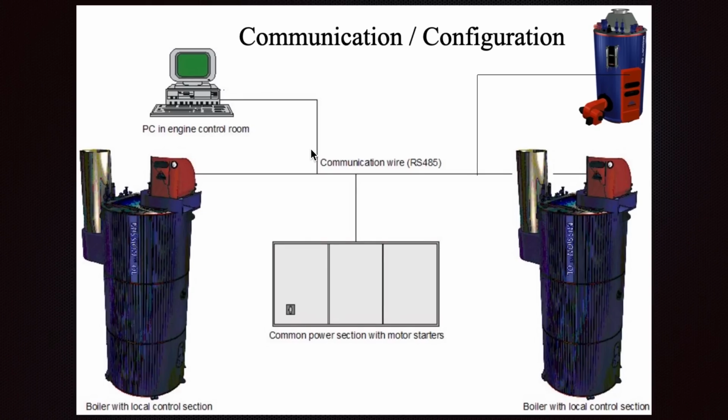So in this case, even if we have some problem with the wire, we can still operate our boiler here. I really suggest you also operate the boiler from the local station, to take the control there, so you will be familiar, and in any emergency, when you are down there, you have your people that can operate, and make some trainings.